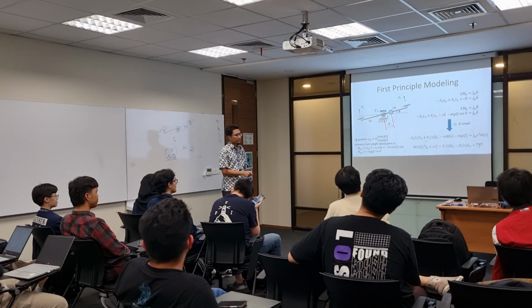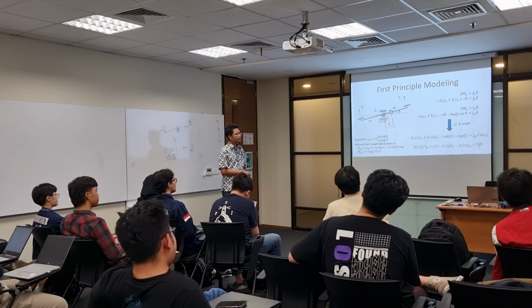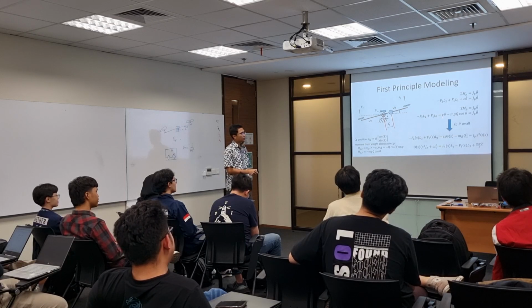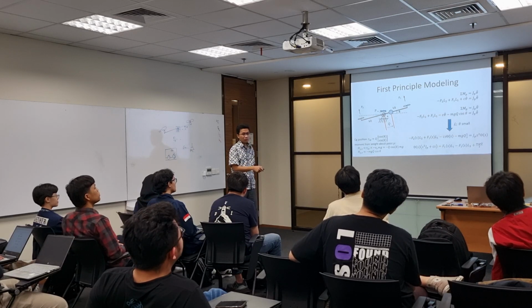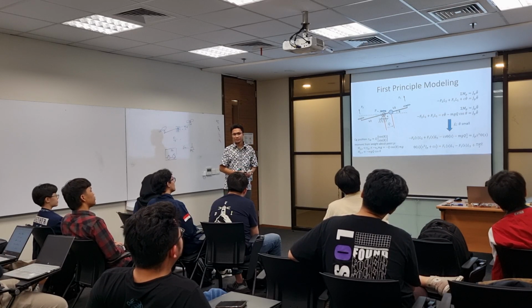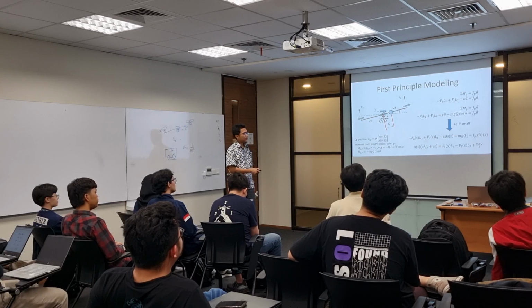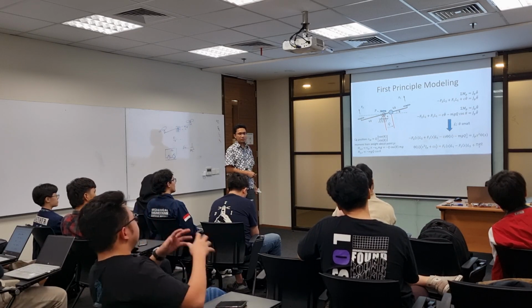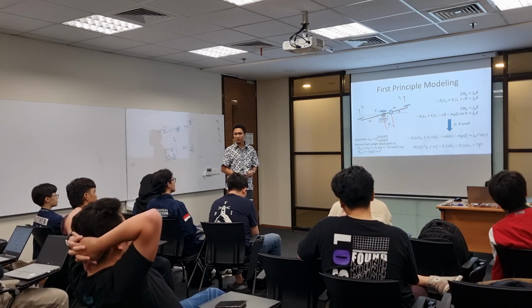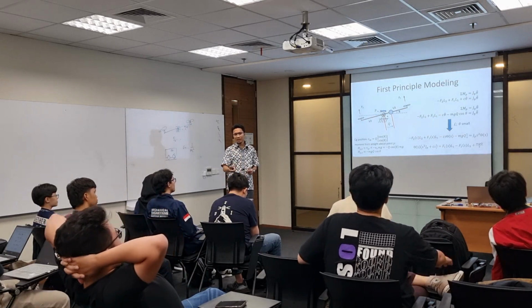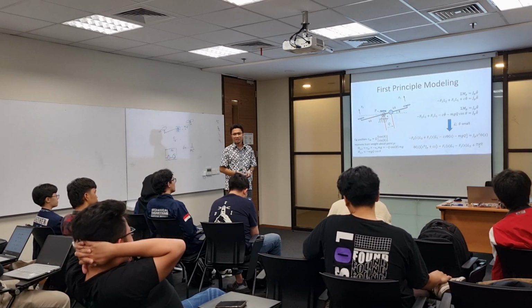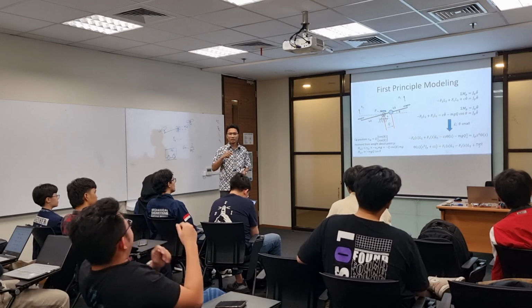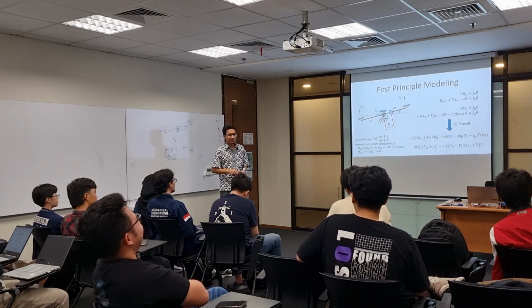We just discussed this part, and then I want to convert the whole thing into the Laplace domain, and I have a problem with the cos theta. So I assume theta is a very small angle, so cos theta I assume to be 1. Not equal to theta, but equal to 1. You make it equal to theta if it is sine theta.